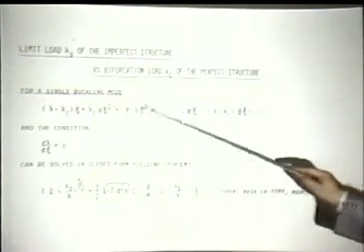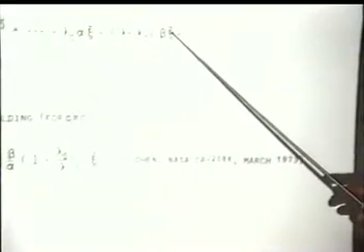Now, there is an old paper by Jerry Cohen, a NASA contractor report, March 1973, where he studies and shows the effect of the first and the second post-buckling coefficient. Remember, he introduced the second post-buckling coefficient, so he obviously had to show why that is important. Now notice the following. This is for a single buckling mode, so this is the equation.